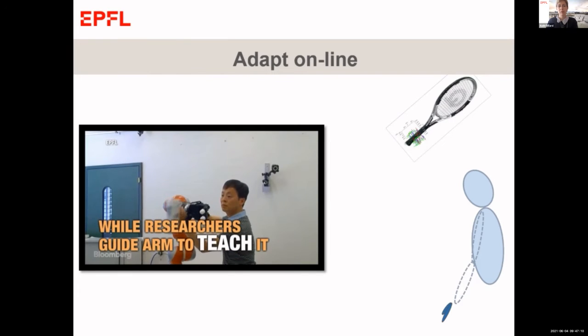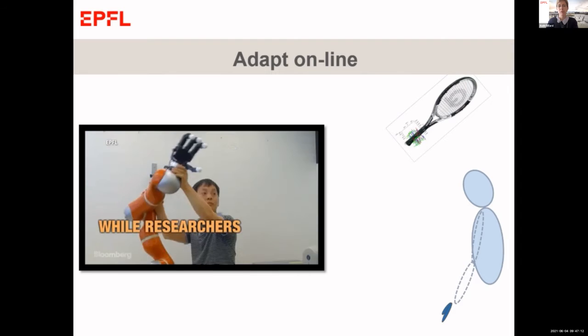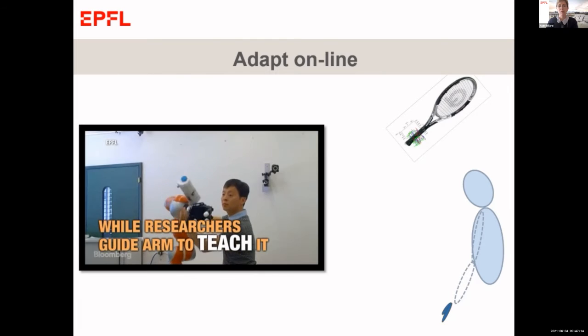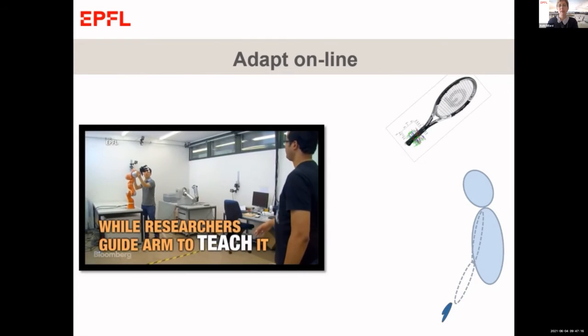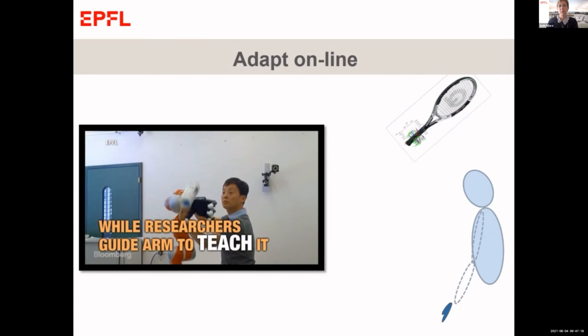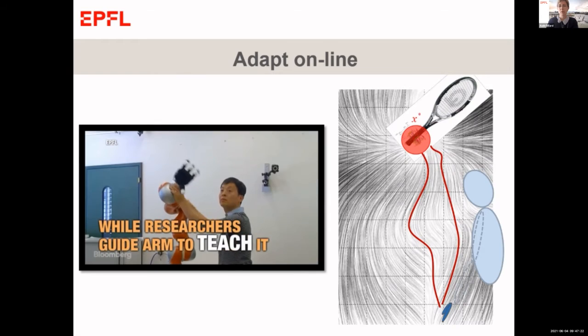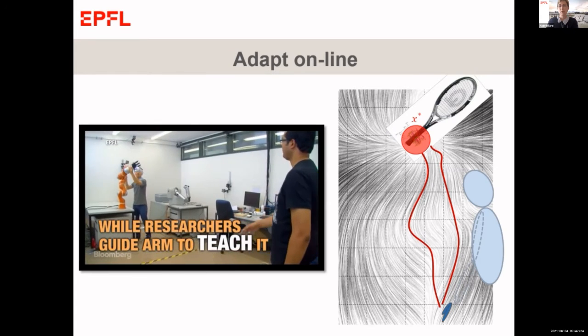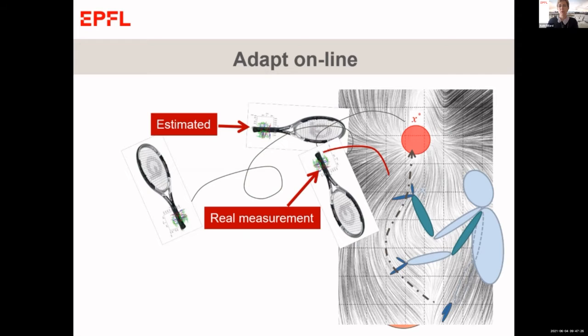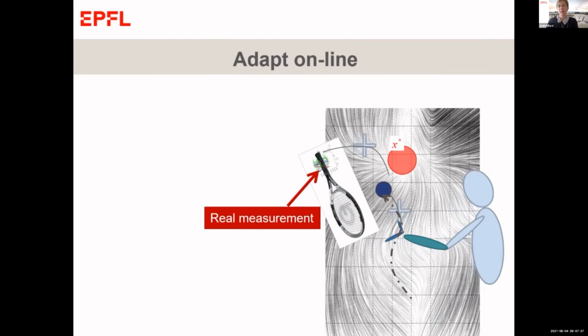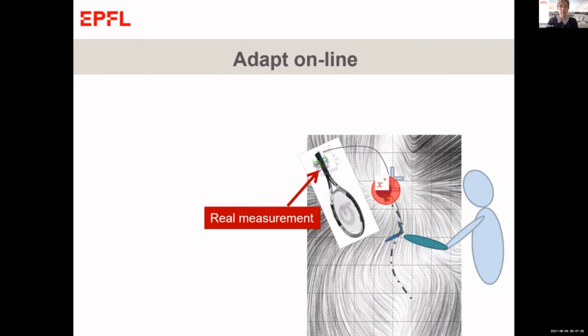So we used, by the way, human demonstration in this case to learn different trajectories to catch, as you can see here, from the robot viewpoint, so that we had kinematically feasible postures. And then from there, we learned a dynamical system, the same way as I explained it before, and we use this in combination. We used also the same trick of putting the origin of the system on the point where we wanted to catch, such that we will have our dynamical system moving with this point.